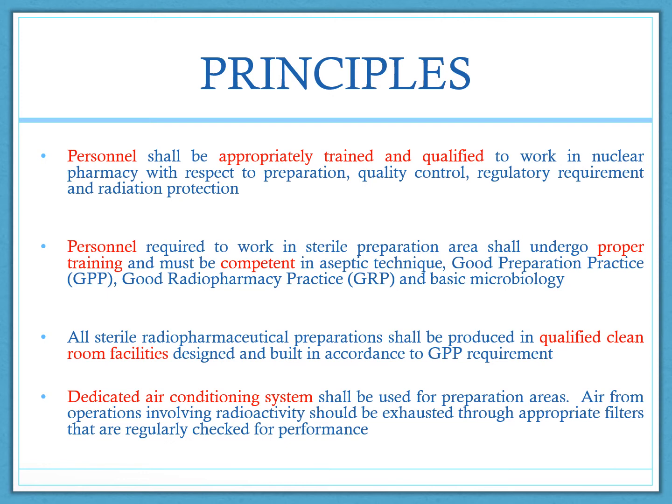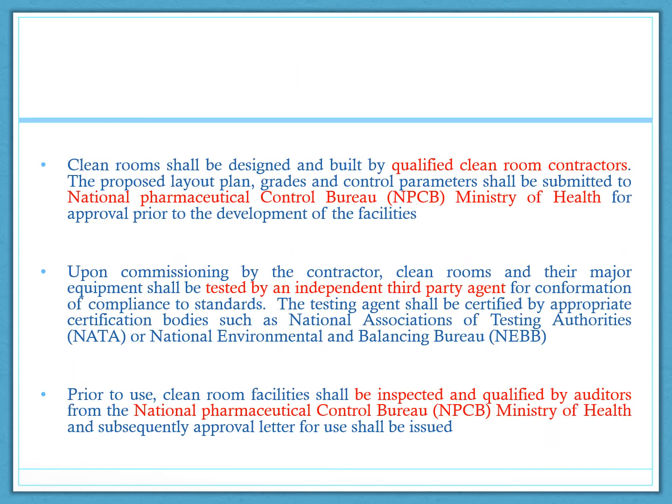The preparation shall be produced in qualified clean room facilities, and they might need a dedicated air conditioning system for its preparation. The clean room shall be designed and built by qualified clean room contractors, as I mentioned just now. The proposed layout, grades, and control parameters shall be submitted to the National Pharmaceutical Control Bureau, or now the National Pharmaceutical Regulatory Agency of the MOH, for approval.